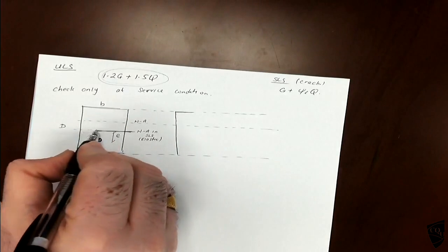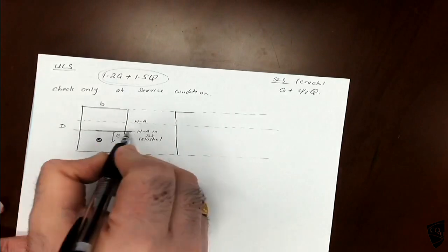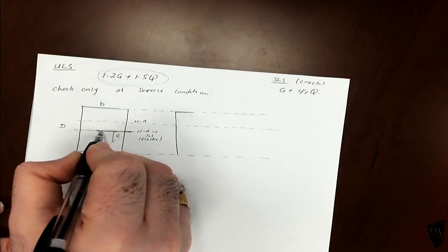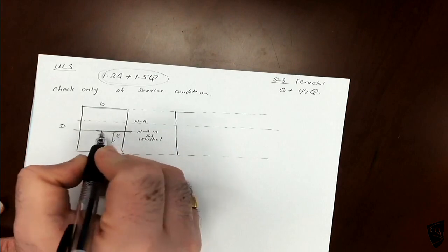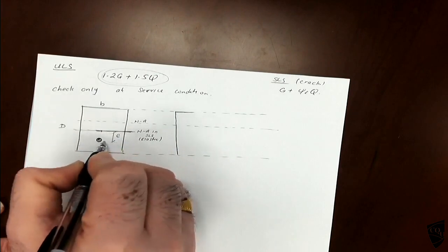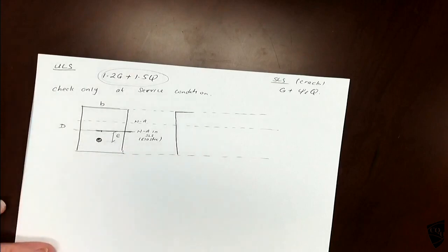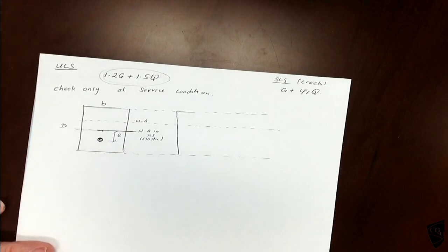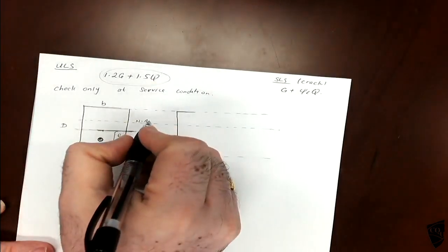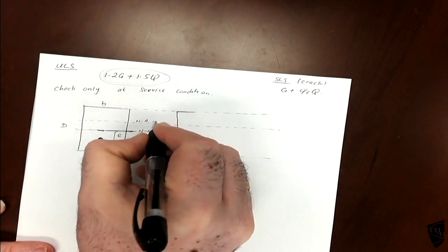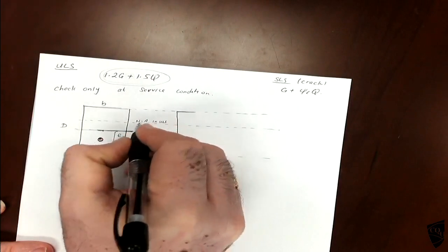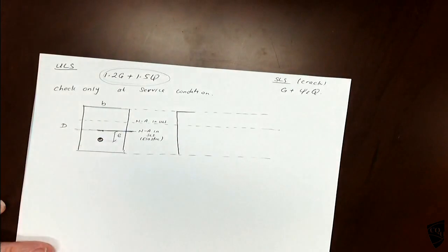This is the previous neutral axis. The previous neutral axis will pass through the centroid. Okay, so the eccentricity was measured from the elastic neutral axis. But now the neutral axis has changed, because the ultimate limit state is not elastic. Okay, so it crossed the elastic limit.